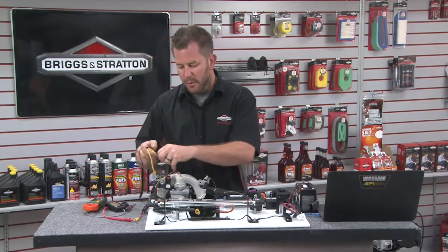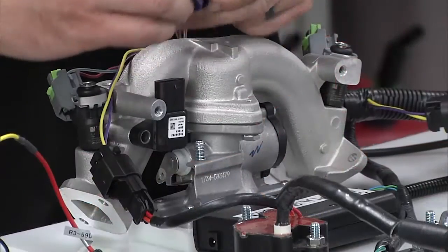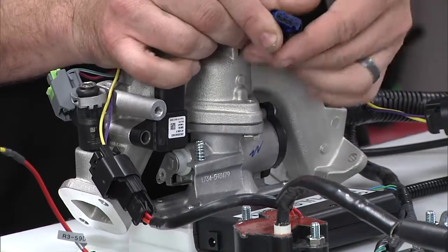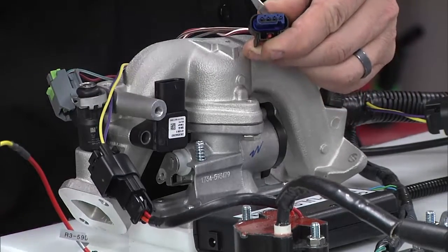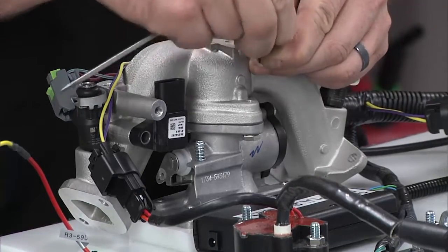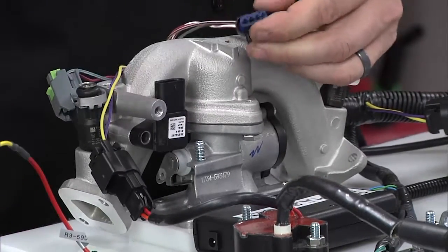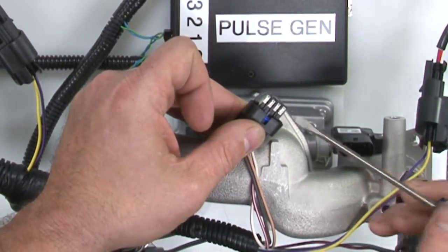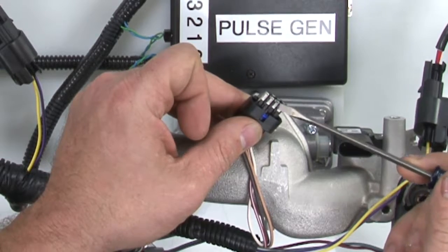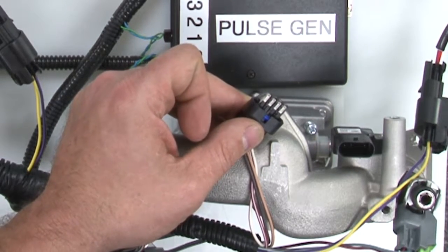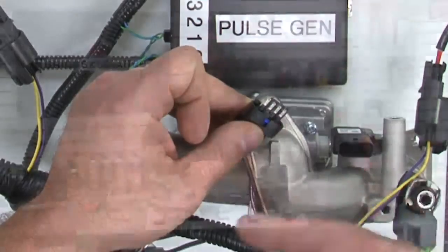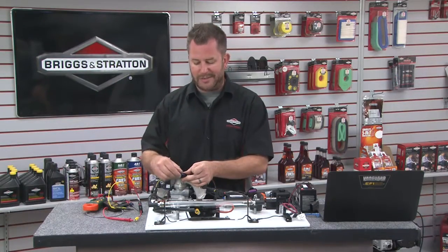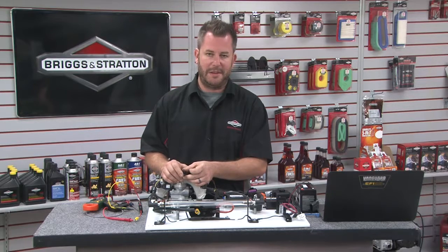Now, what you can do here to kind of verify everything else is good is you would look at the terminals here themselves. You would take this little blue locking clip off here. I'll demonstrate for you. Remove this. It's a little tricky here. You got to get it. There we go. And I can see that all of my terminals are at the same height here. So I'm okay there. Again, you could take it a step further and then look at whether the terminal itself has actually crimped the copper wire. I would argue that it is okay because the computer is seeing the difference there.